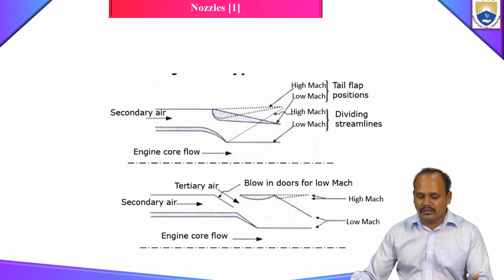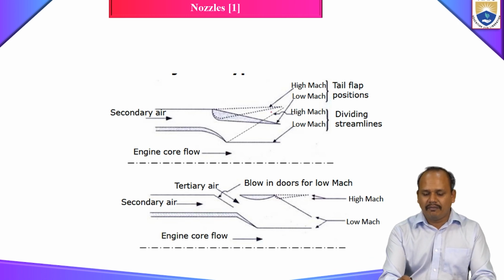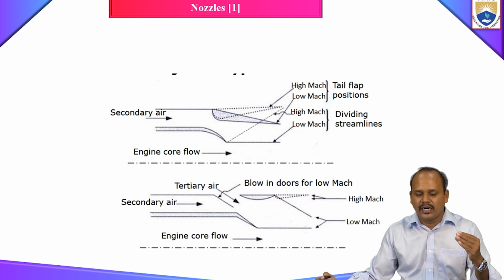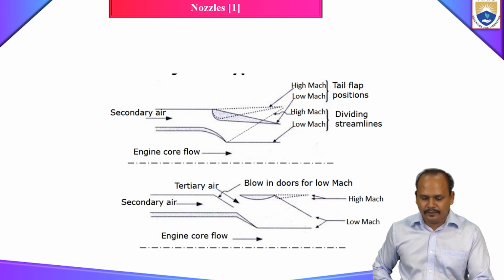So with this flap mechanism, let's say if you want supersonic flow, you will make your flap arrangement like this. If I increase this flap, this same nozzle will become a convergent-divergent nozzle. So based on your back pressure and your inlet pressure, you can adjust your area ratio so that you can operate your nozzle always at a correctly expanded case.